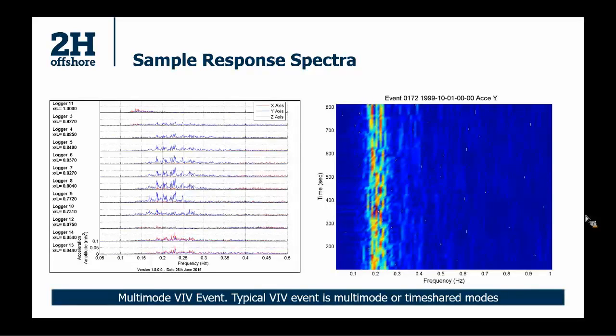And here I'm showing you a VIV response, a multi-mode VIV response. So multiple modes occurring at the same time or occurring one after the other. In the waterfall plot on the right side, you can see these same frequencies. They are switching between each other.